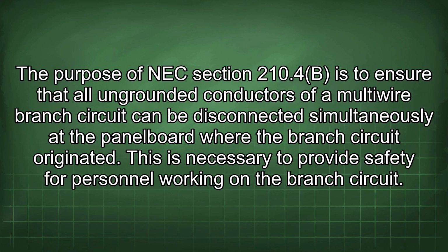The purpose of NEC Section 210.4(B) is to ensure that all ungrounded conductors of a multi-wire branch circuit can be disconnected simultaneously at the panel board where the branch circuit originated. This is necessary to provide safety for personnel working on the branch circuit.